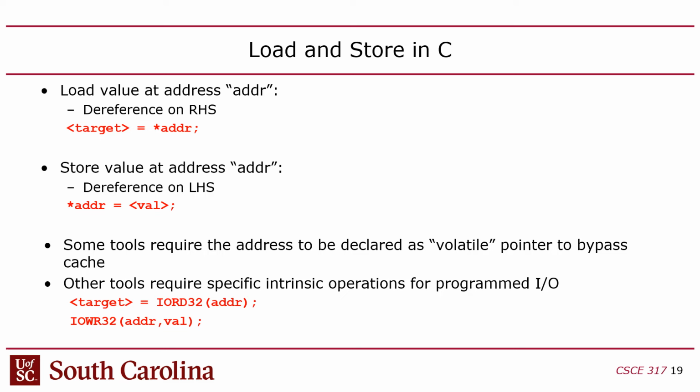But sometimes you have to use these intrinsics instead, which are explicit ways to do I/O reads or I/O writes using a macro. An intrinsic is a word that means it's like a function call or a macro, but if you call it an intrinsic, it means that it maps specifically to one hardware instruction. And so this would map to one hardware instruction. Although technically, when you put the address in there, it may expand. There might be several instructions generated to compute that address.